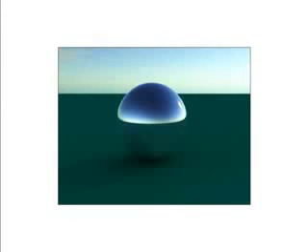Now let's look at a sequence of images where the HDRI that was used to illuminate the scene is also being used as the background. Here you can see the background in the distance and also reflected in the sphere. As the HDRI is rotated around the scene, you can see the illumination change accordingly. The side of the scene with the sun receives greater illumination than other parts, and you can see the shadows change as the background is rotated.